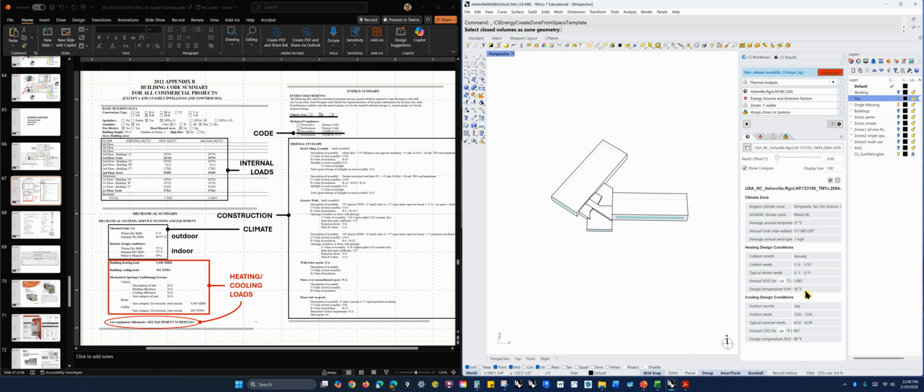And remember, the idea here is that we need to design a system that's going to experience the peak heating and cooling loads, but we don't want to design it for every single hour of the year. So you can see right here, this is 0.04. There's 4/100ths of the number of hours of the year that are below this temperature. And we're saying, you'll wear a sweater. We'll have little space heaters under people's desks or something for those. Or maybe these hours are probably going to be at night, and if it's a school, there's not going to even be people there. So that's the thought process behind it.